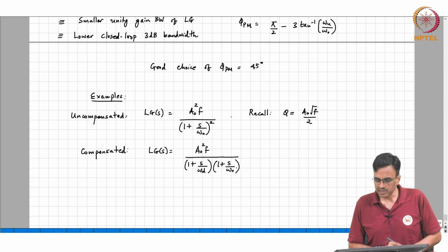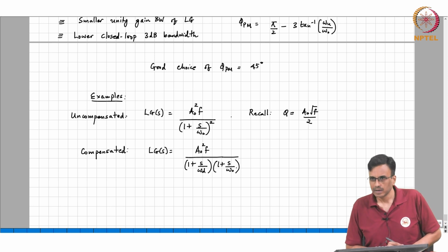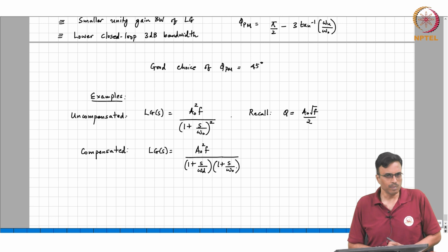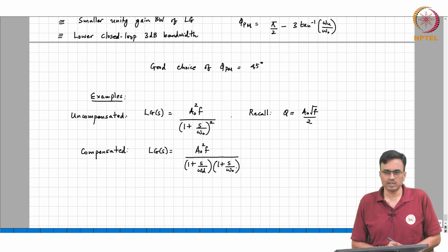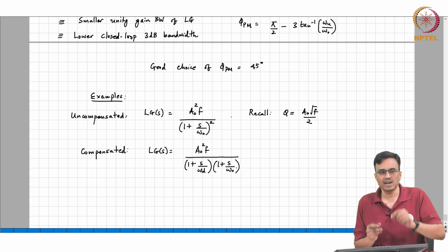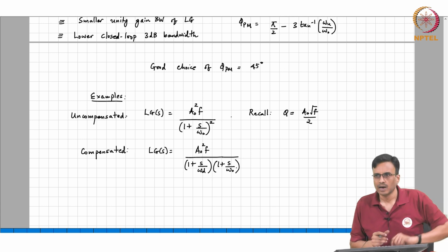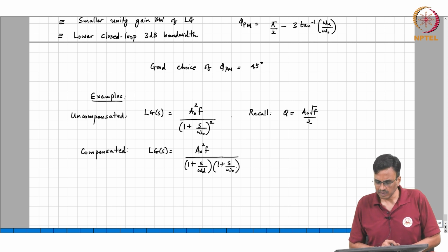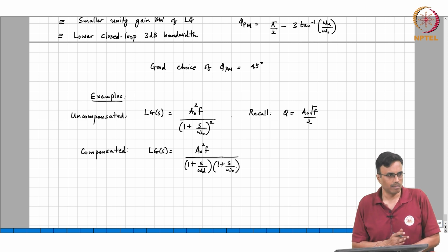One of the poles has been made deliberately lower, and in circuits that is easily done because the poles all come from some parasitic capacitance somewhere. You can take a big intentional capacitor and put it in parallel with one of the existing parasitic capacitances, and therefore one of those poles can become dominant, right.